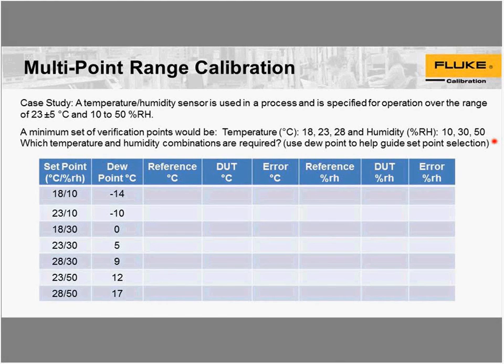Hold the metal sheath so that you can connect a resistance meter to the sheath and then the other probe to one of the lead wires of the sensor, to check for leakage as well. I guess it doesn't matter which one you start with first, but you can put the probe at a temperature that's well below zero, like minus 40. That will definitely create a negative pressure and cause it to pull moisture inside the sensor.